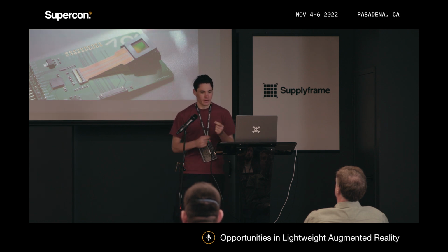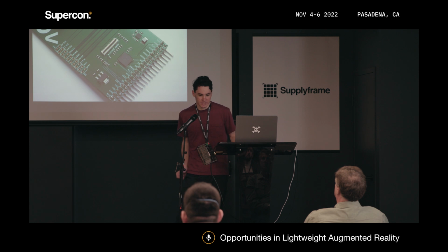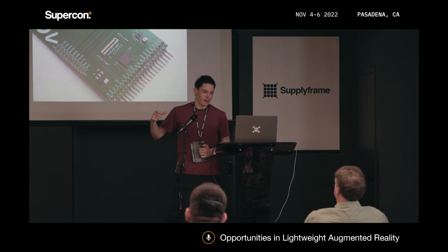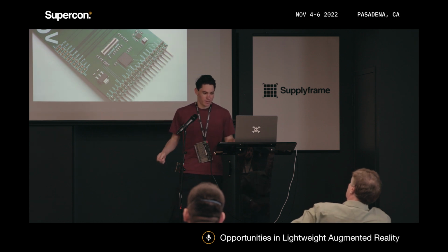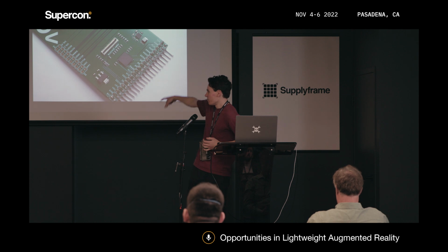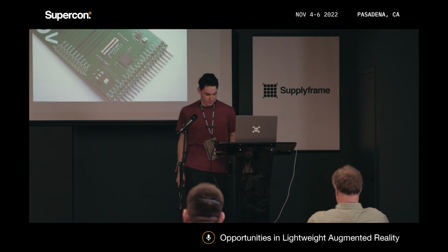They're essentially a single silicon backplane with an OLED display on it. This particular one is ECX337A. I designed a board to test it. I didn't use someone else's breakout board, I just went straight to designing my own. So it essentially has a parallel interface, a parallel RGB to LVDS bridge chip, and then the display attached.